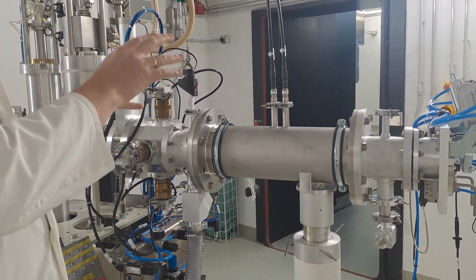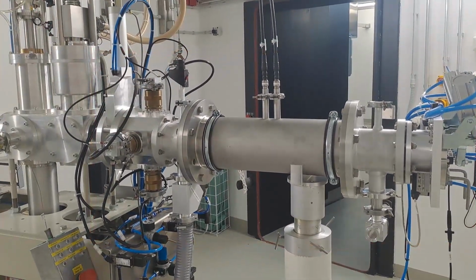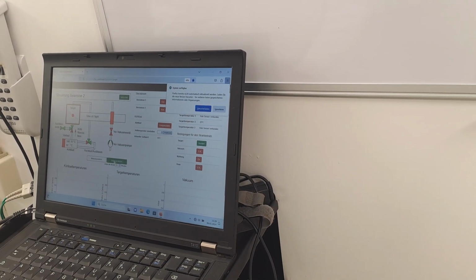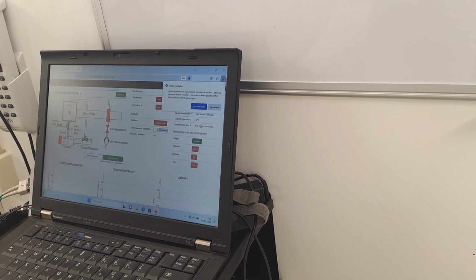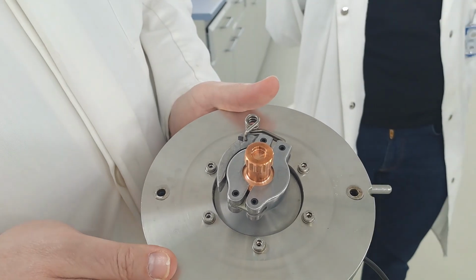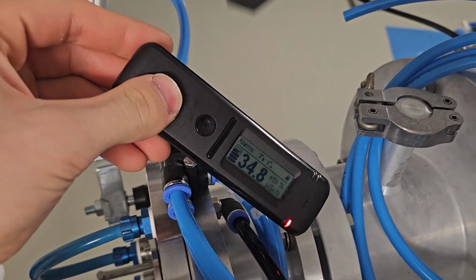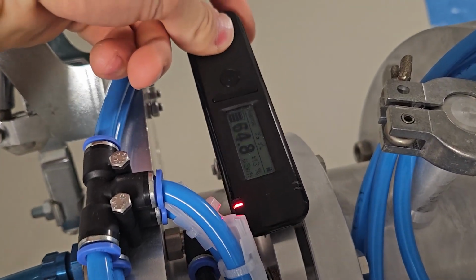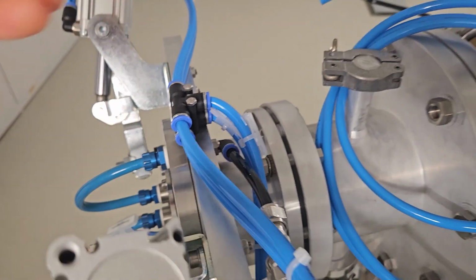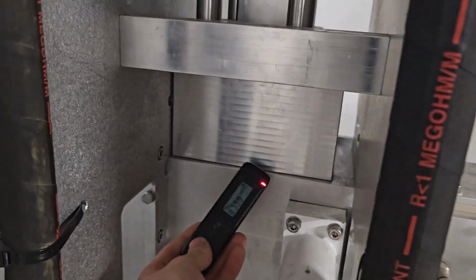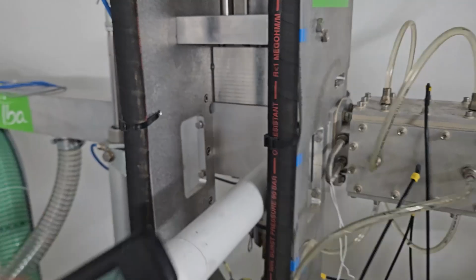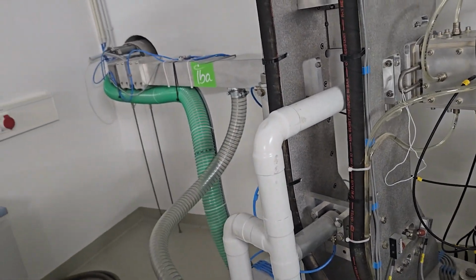Both the software and these parts of the hardware are custom built, requiring top-notch workshop skills that I can't even fathom. With this software, everything can be controlled from vacuum systems to hose cleaning and compressed air. Solid targets are clamped into these copper holders, and after irradiation, other components, including the quadrupole magnets, also become activated, reaching up to 70 microsieverts an hour or nearly half a millisievert per hour at another beamline. This footage was taken on a Monday, so not much irradiation happened over the weekend.